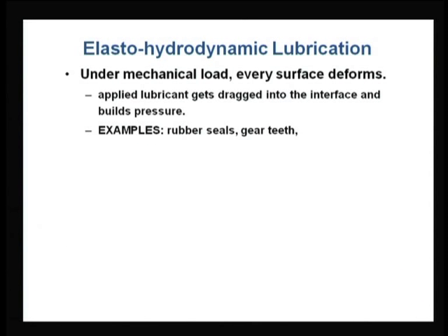Now, some interesting things about elasto-hydrodynamic lubrication, or some sort of mechanism which can be proposed. When we say that under mechanical loads, every surface deforms. This is by and large true. Deformation may be at a nano level, but deformation will surely be there. And if there is a deformation, there is a possibility of dragging the lubricant into that interface. And if there is a dragging of lubricant at the interface, pressure will increase.